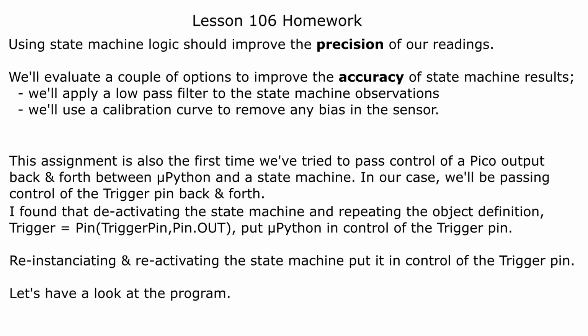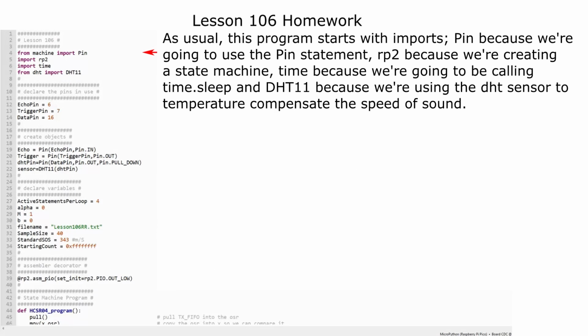Let's have a look at the program. As usual, this program starts with imports. We import pin because we're going to be using the pin statement, RP2 because we're creating a state machine, time because we're going to be calling time.sleep, and DHT11 because we're using the DHT sensor to temperature compensate the speed